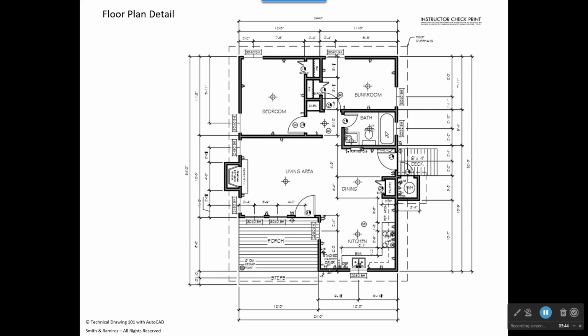It has only 1 bathroom, and it has an overhead light in there that has a vent. It has a light, and it has a heater built into this entire thing. So we're going to actually have 3 switches over here on this wall, all feeding to what looks like a light. But as I said, the light has a vent and a heater as well as a light built into it.